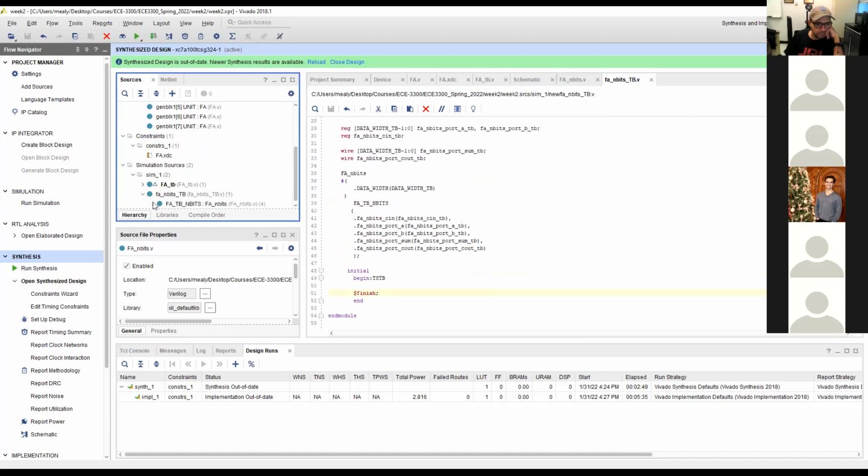The overwriting here helps us look into the test bench. If you look very carefully, if you go there, you will find that we already have 4 units, even though there we have 8 units. So the parameter overwrite. And we looked into how we can make it completely flexible and generic using generate for loop with genvar to define the indexing inside the for loop. If you have any questions or concerns, please let me know. A copy of this code and a copy of the recorded video will be posted on Canvas under modules week number 2. Thanks so much. And I think you already have a copy of the slides. We haven't finished it yet from last week.